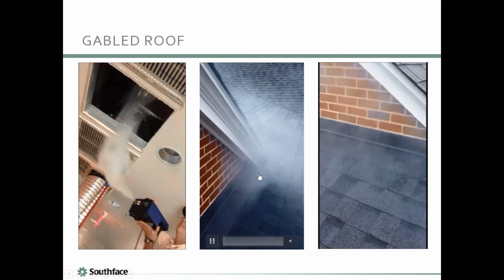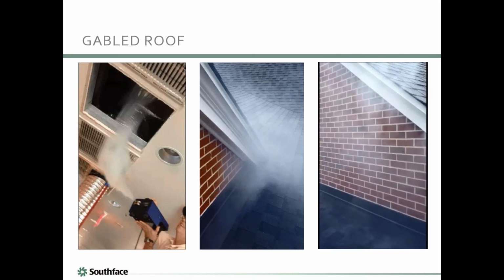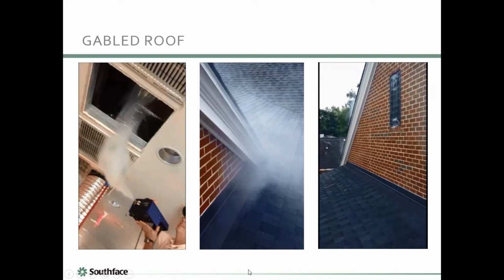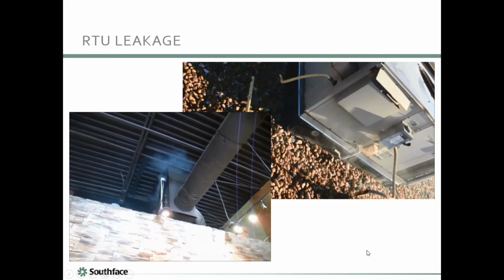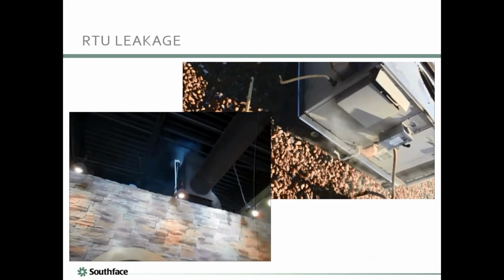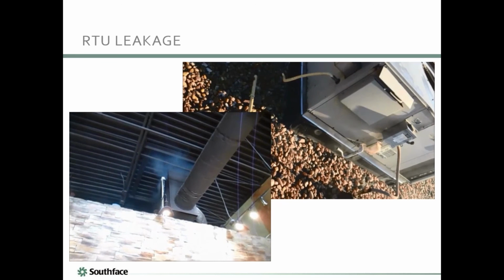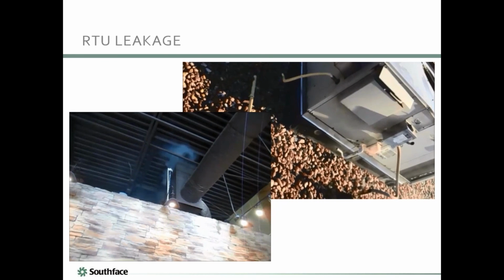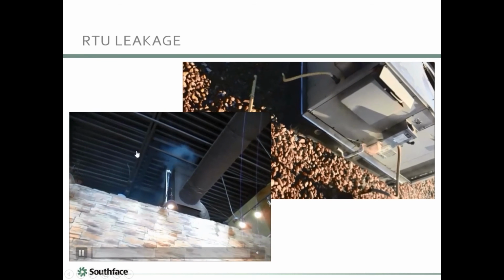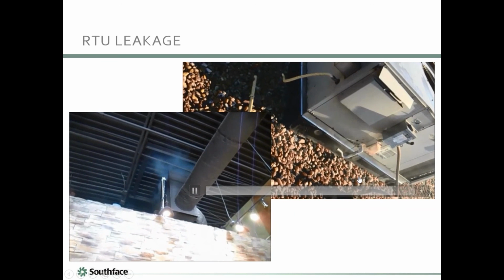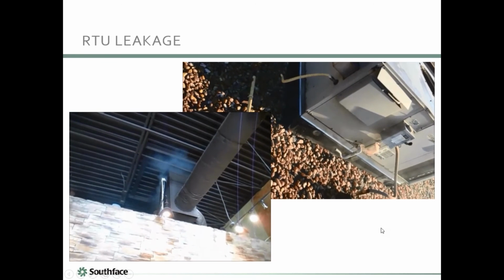Lots of leaks. They came back and foamed the roof line, which sounds like, okay, great, we solved all the problems, but they couldn't get access to some of these places, or they didn't access some of these places. And when we pressurized it, the fog essentially went out. I believe there was a structural metal box beam that penetrated, and that was not sealed at all. So huge leak path, and it looks like it's just coming out of the roof itself, leaking out of this unvented roof assembly. So excitement there.